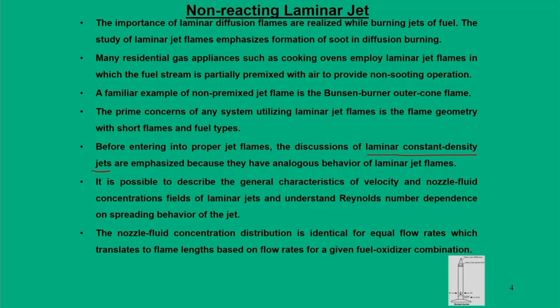That means if you simulate the actual behavior, density keeps on changing during the combustion process, because the products are formed. But when you say constant density, we assume that it is non-reacting, but we are choosing a fuel in such a way that the behavior is analogous to the actual jet flame. So, through this analysis, it will be possible to establish the general characteristics of velocity and nozzle fluid concentration fields of laminar jets, and understand the Reynolds number dependence of the spreading behavior of the jet.